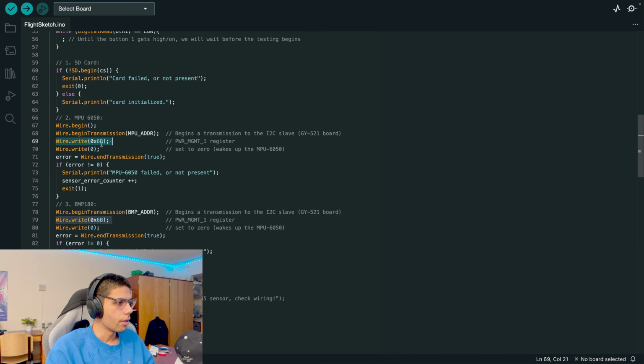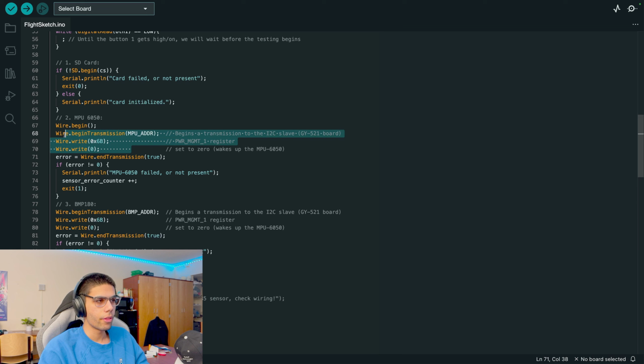And I said to start writing in that register one, Wire.write set to 0. If everything worked till here, that means your connections are correct. Now your connection is actually activated, and they can communicate between them.